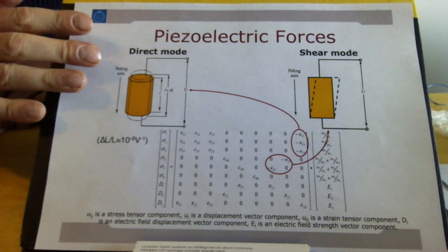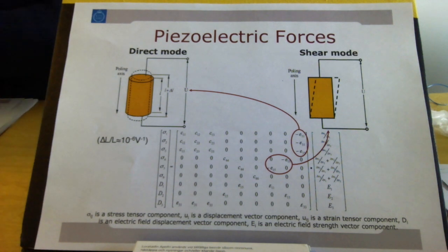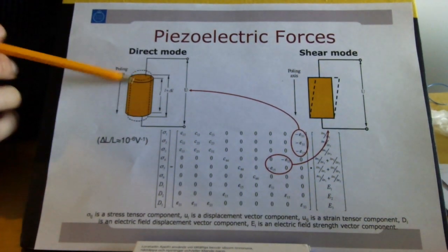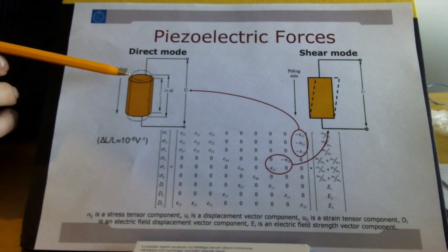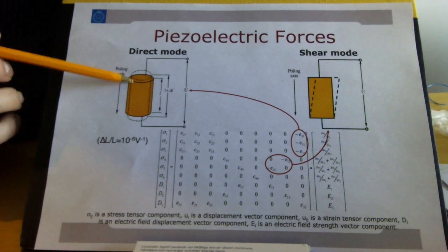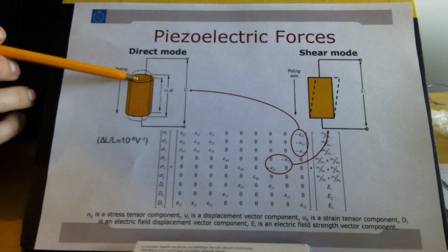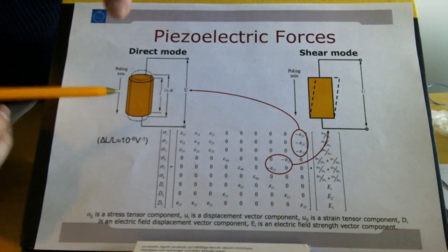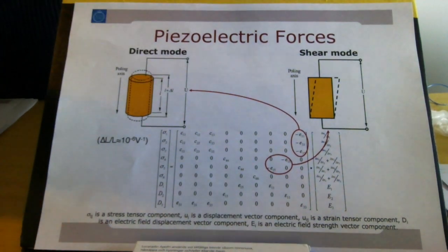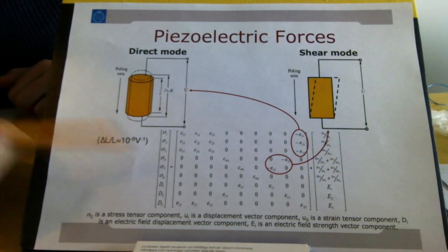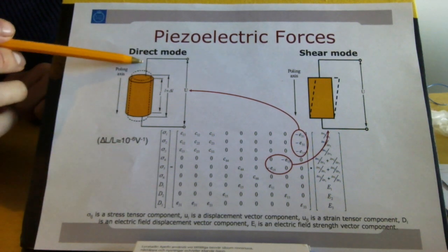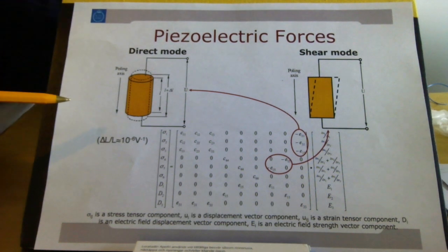How do you deal with piezoelectricity? There's something called the piezoelectric coefficient. A piezoelectric material can, of course, be strained in 3 different directions, so you have different stress tensors. You can strain it in different ways, like horizontal, vertical, and in the horizontal plane. And you can also shear it in 3 different directions. So you get 6 different stress terms. And then, of course, you also have an electric field or dielectric field in the 3 spatial dimensions.